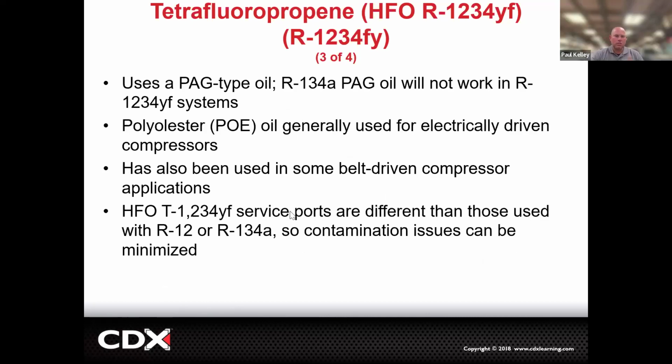And then you notice it uses a PAG oil, but it's a slightly different PAG oil. So if you have R134A PAG oil, that's good for R134A. But if you have R1234yf, it should be an R1234yf PAG oil, not the same, just a little different.